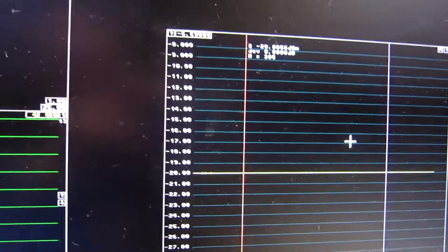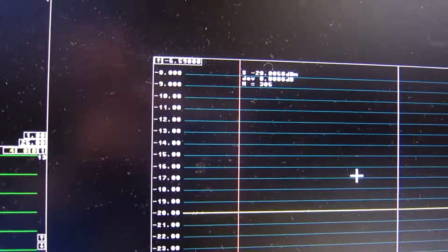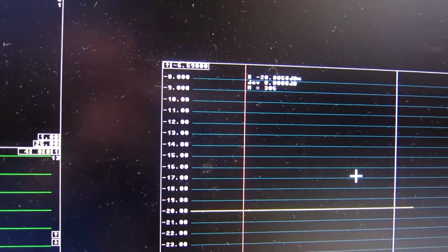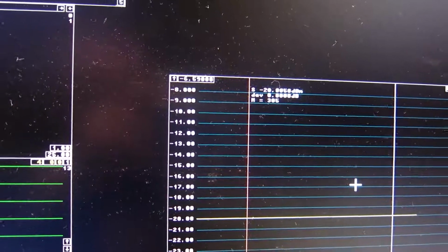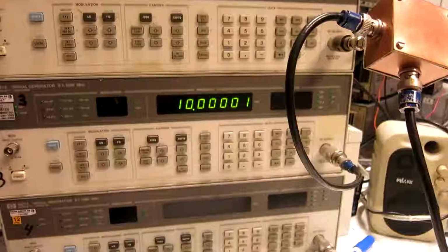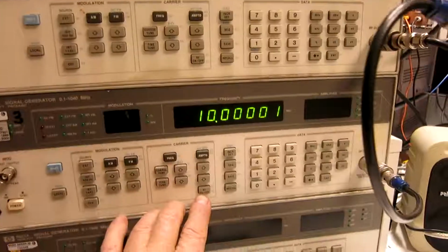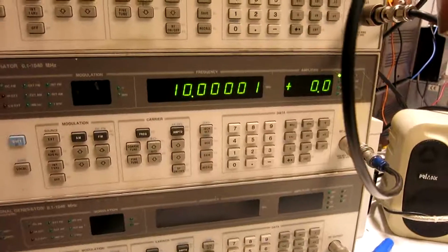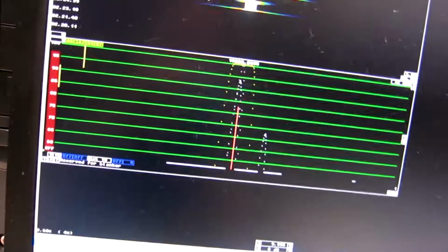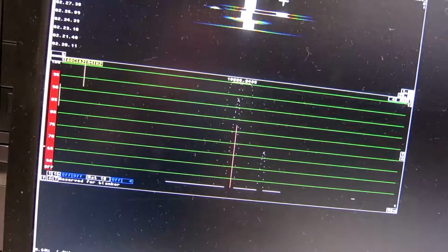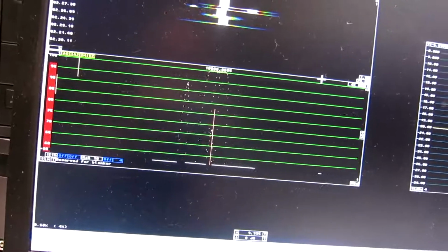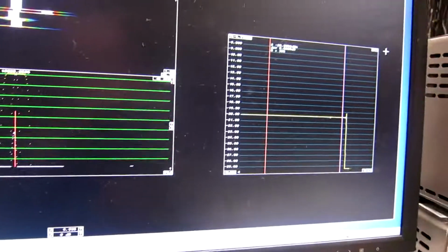And I have calibrated the level to show minus 20 dB. That is the 20 dB setting on the attenuator. And I now add a signal 10 Hz up in frequency. And it comes here. And things are slow because I have a narrow bandwidth.